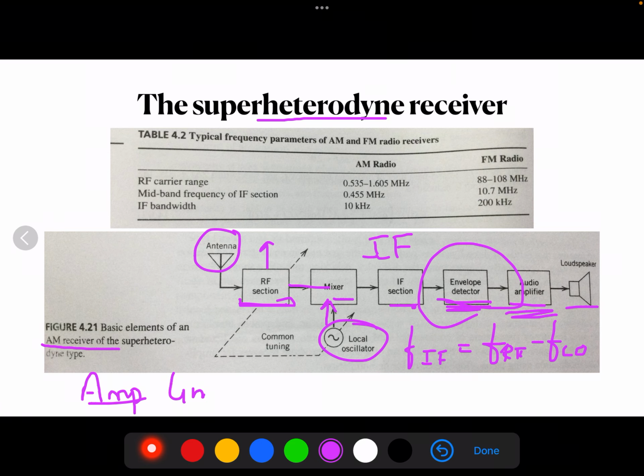So we use the amplitude limiter. If there are any variations in the amplitude of the FM signal, we use the amplitude limiter. It is basically used to remove amplitude variations by clipping the modulated wave at the IF section output. The resulting square wave is rounded off by a band pass filter. It suppresses the harmonics of the carrier wave, so the output we get is a pure sine wave.